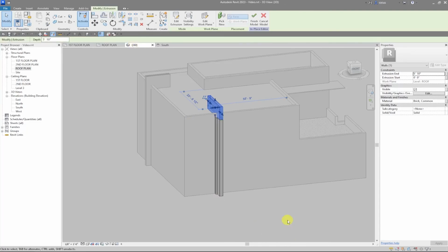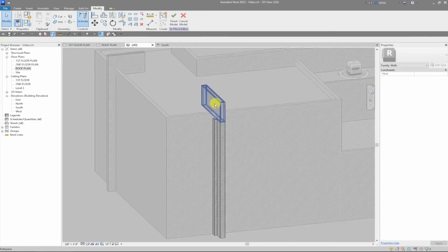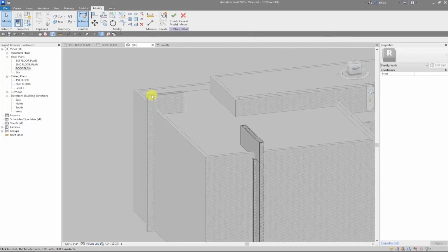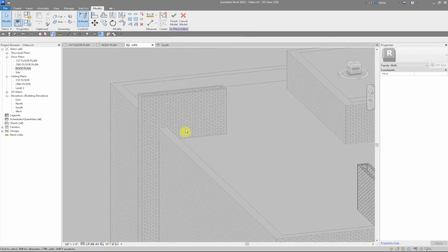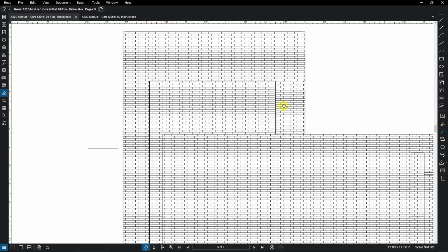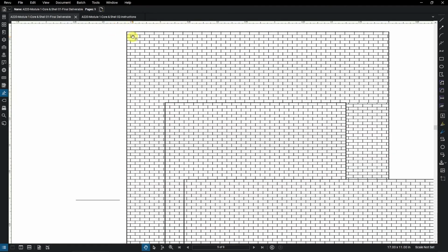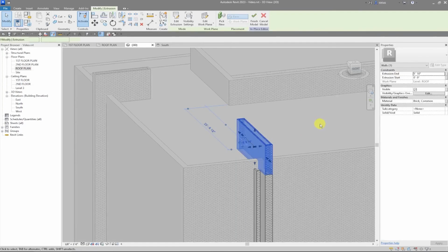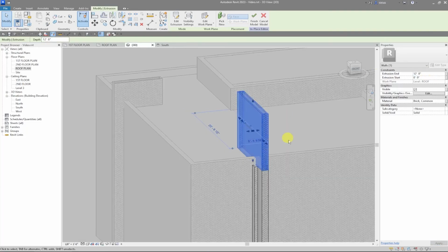3D. So you can see how that works. Now that's going to be much taller than that. In fact, I don't even think I checked the height of this. So check the height in your elevations. I may have forgotten it initially, so you might have to count bricks. We know how tall a brick is, and 3 bricks equals 8 inches, so I'm going to go 1, 2, 3, 1, 2, 3, 19. So there's 19 times 8, 152 inches. So I can come back in here, select this thing, and say 152 inches, which ends up being 12'8". So that's the height of that.